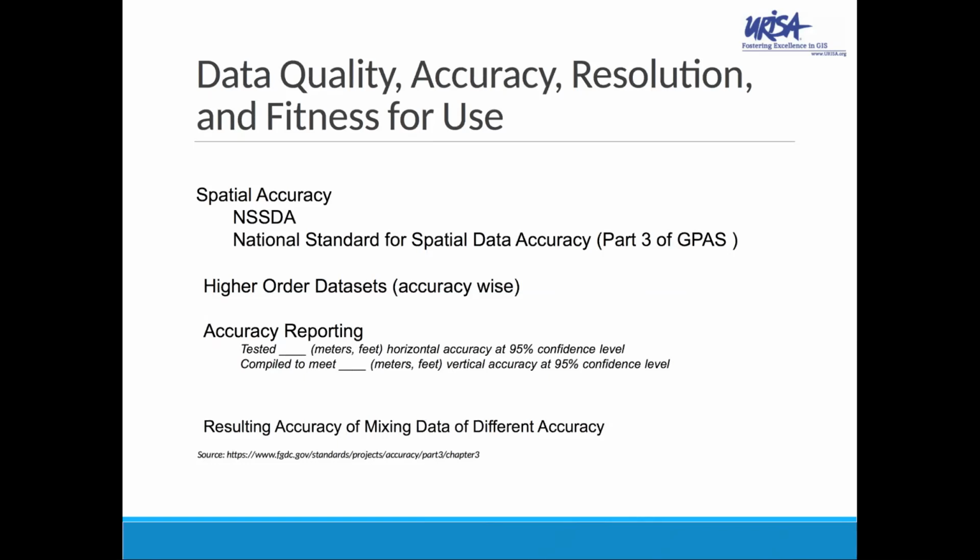If I did a raster masking of vector data, and the raster data had a horizontal error, an E95, of 10 feet, and the vector data had an E95 of 5 feet, and I mixed them together, in what way have I hurt the resulting information, and to what degree? Know your error reporting samples so that you're able to report that correctly without causing confusion.